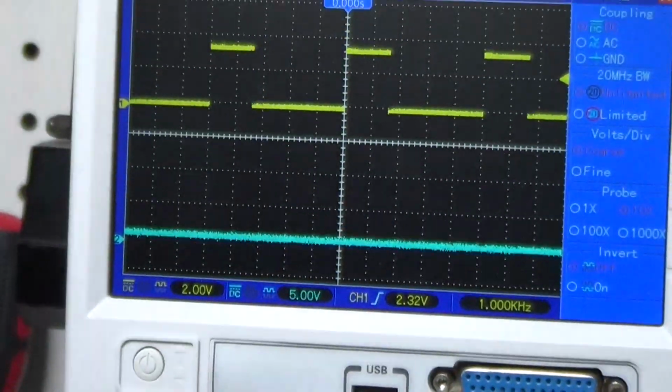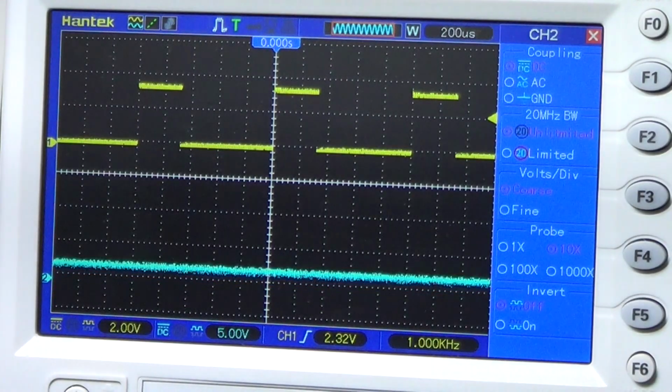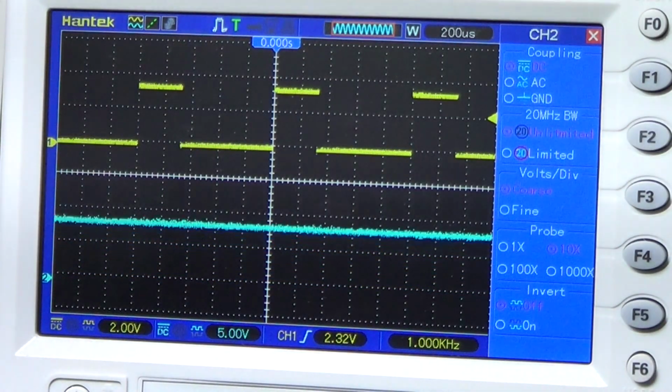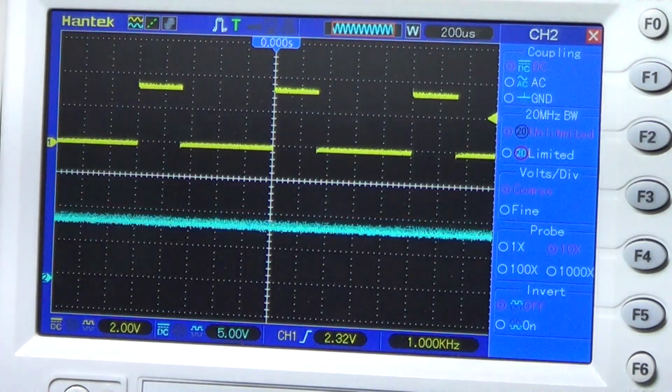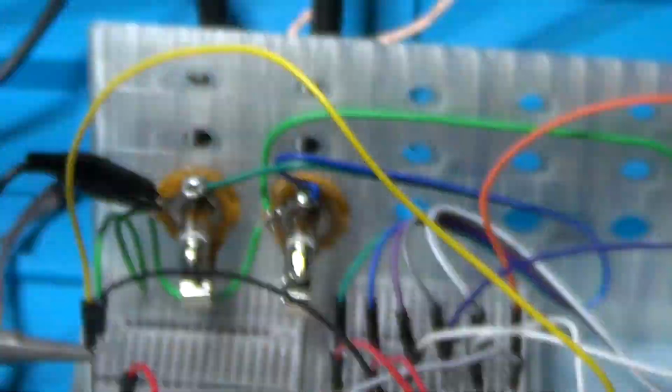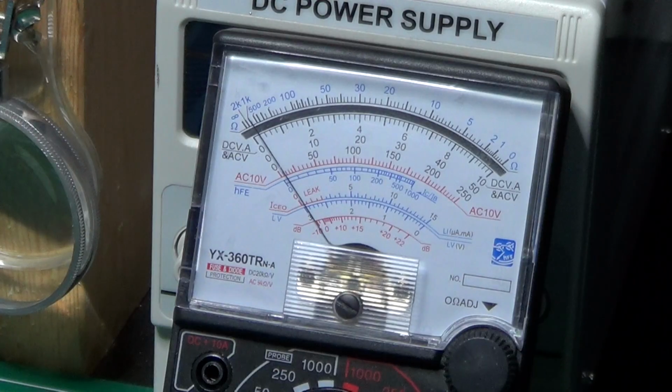Let's now compare with the controller K5, watching the blue trace on the oscilloscope. And you can see that since we are now going through the filter and the amplifier, only the average voltage of the square wave is visible, and it changes while rotating the knob. And finally, if we use K6, we can see the effect of the analog multimeter, which shows a fluid and continuous movement of the pointer on its scale, corresponding to the movement of the potentiometer knob.